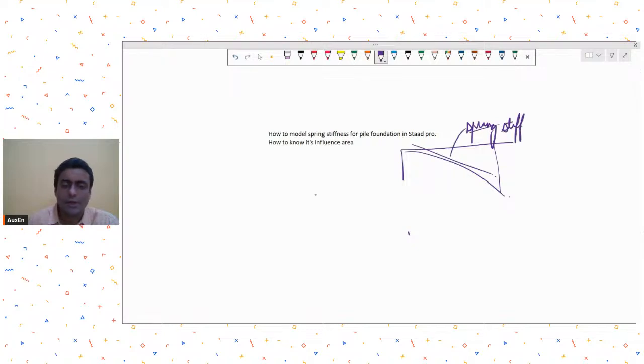So this slope will give you the spring stiffness of pile. If not, then let's say you have the capacity of pile in compression. Now usually the capacity of the pile in compression is 2/3 of the total capacity at which 12 mm settlement takes place. So what you do is some reverse working. So let's say capacity of pile has been given as 10 tons. Now what is this 10 tons? This is 2/3 of the load at which 12 mm settlement took place. So you try and calculate this P.